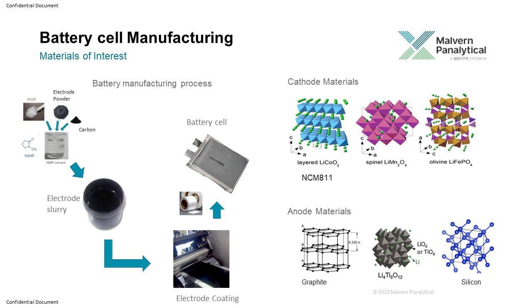So the most popular chemistry nowadays is the NCM 811, where nickel is 80%, cobalt is 10%, and manganese is 10%. Because this chemistry gives you the highest energy density. Although to stabilize this chemistry, there is some kind of art and some kind of IP technologies that are involved. It is not so easy to stabilize this chemistry, but once stabilized, that gives the highest energy density.